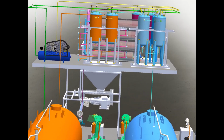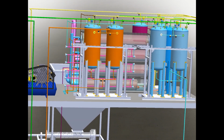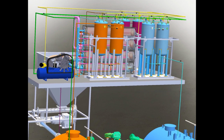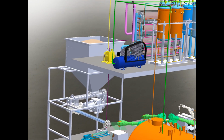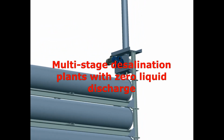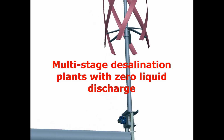In nuclear energy, dose loads on personnel are sharply reduced due to the absence of the need to clean heat exchange tubes from deposits. Low operating costs. Convenient integration into a continuous technological cycle. The most promising direction for mass production of film evaporation drum, FED, is the production of multi-stage desalination plants with zero liquid discharge.